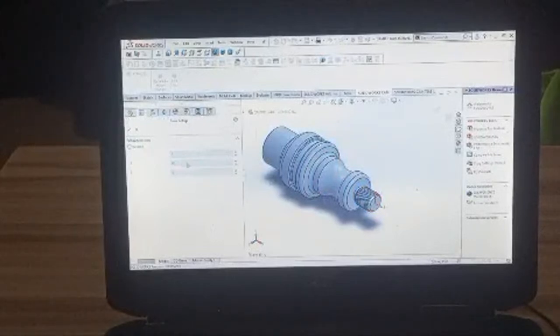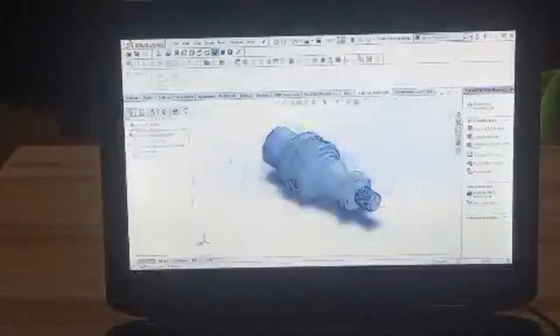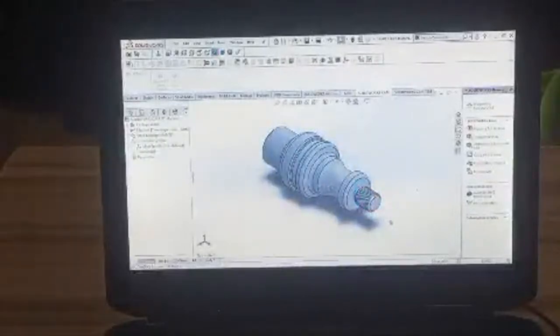You click OK. This one doesn't mean that this is zero, but it actually means that this is where the tool for turning will be coming from. Actually, it's by default. Then you click OK. So that's where our code system is.